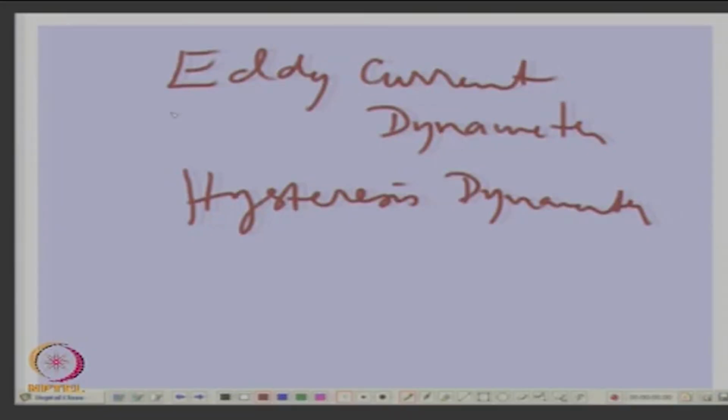Therefore, in an eddy current dynamometer, the heat is due to eddy current flowing in a disc. For a shaft you connect a disc, and have a magnet or something like that. It will induce an eddy current in them, so that it becomes a loss, it will generate a negative torque or loads the motor.